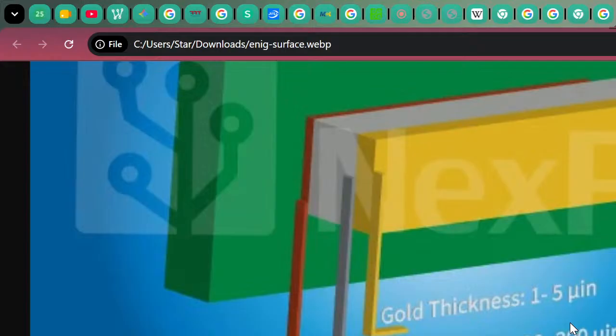But the actual implementation is a little bit varying. It is a little bit deviating from the actual specification. I don't reject whatever the values are specified. See, for nickel, it is within limit. If you reduce 5 micro inch thickness, it's perfectly 100 to 200. This range is very good. Gold is also very good, 1 to 5. So no need to put that much micro inch thickness. Not necessary. That is as per the specification, but the range would be a little bit different.